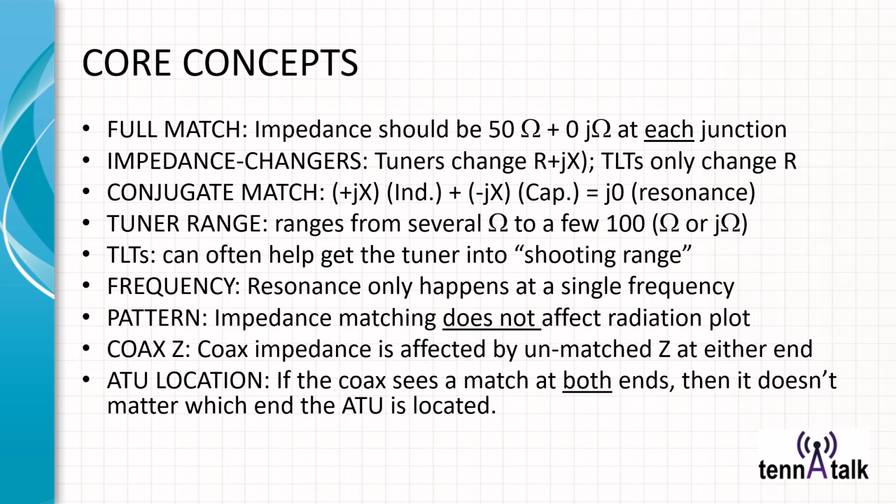And with respect to ATU location, if the coax sees a match at both ends, then it doesn't matter which end the ATU is located at. You won't see a difference. You'll get an equal amount of loss either way. But that's not a normal situation, but it can happen.